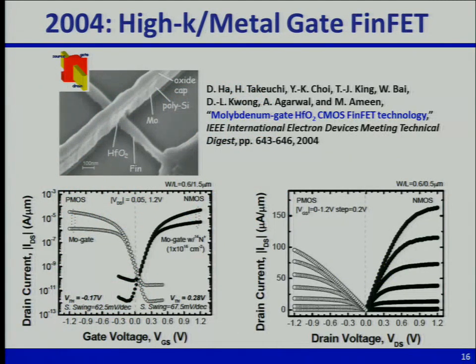All right, so as I mentioned last time, the FinFET was introduced only this decade. In the last decade, what has the industry done? It introduced strained silicon, and it introduced high-K metal gate. So of course, we had to show that the FinFET was compatible with high-K metal gate materials, and indeed, we demonstrated molybdenum as a gate material and hafnium dioxide as a high permittivity gate dielectric for NMOS and PMOS devices,